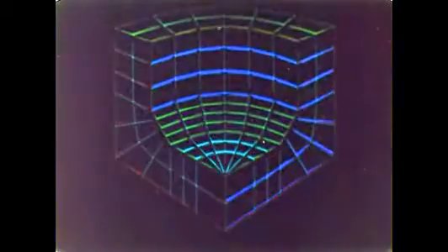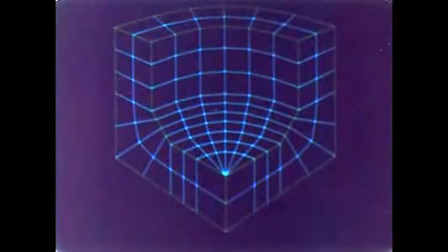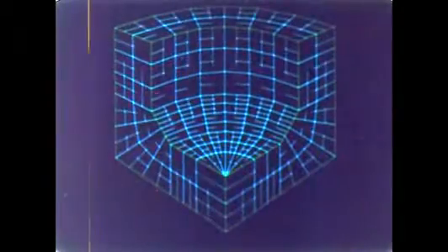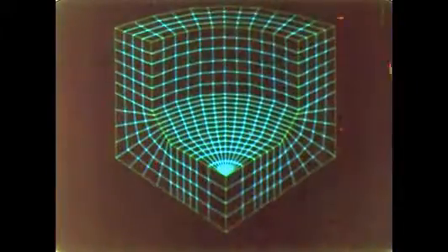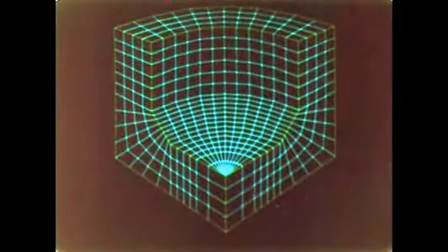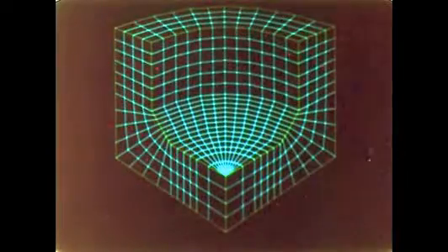The accuracy of the calculation is going to depend on the number of elements we choose to have in the mesh. The more elements we have, the smaller each one will be, and the more accurate the results. Unfortunately, more elements also means more calculations to be done. For reasons of economy, therefore, we look for the happy medium, just enough elements to give adequate accuracy within a reasonable computing time.